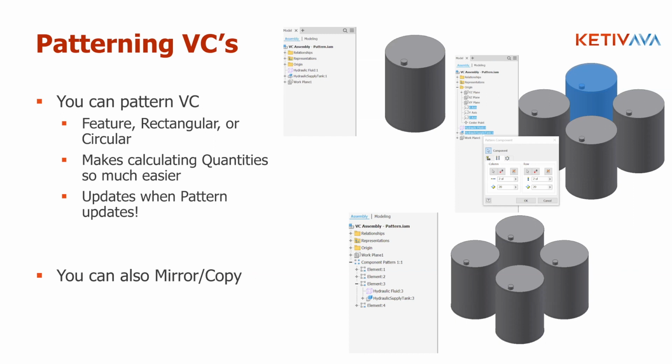I was curious if it would follow kind of the rules of a part, even if we were in, say, a pattern or mirror copy. I know there's some workflows you can get into so you can disassociate those. So maybe can you remove association from a pattern and then be able to modify that part? No, okay. Unfortunately you can't. And there's nothing directly to do like a component replace with copy.